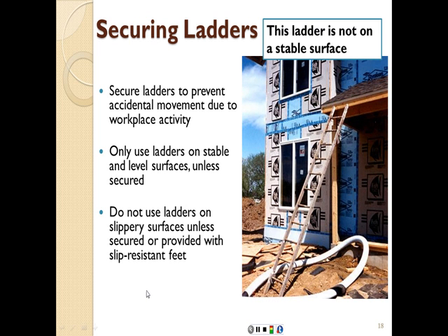Do not use ladders on slippery surfaces unless secured or provided with slip resistant feet. Some rubbery material can hold itself and prevent the ladder from moving or slipping due to that slippery material. We're going to see later on there's another violation here as well, because we have another issue with ladders extending beyond the landing surface. We're going to see that in a moment.